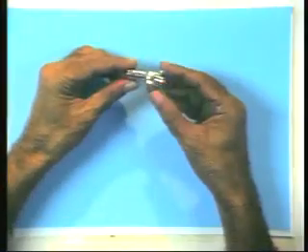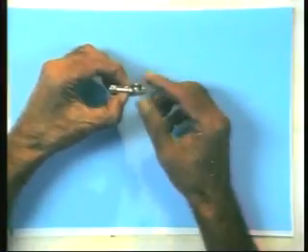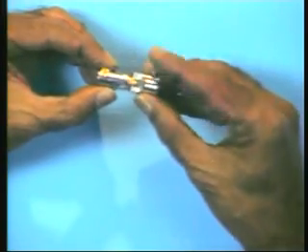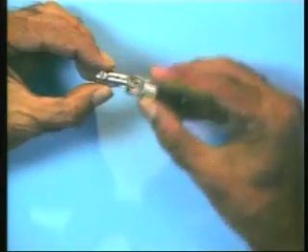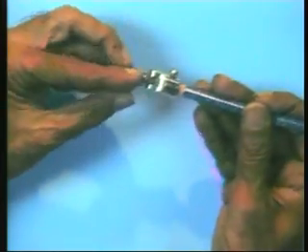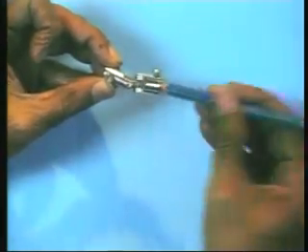See, here is a hook joint. Let me put that paper on top and show you the hook joint. It's a very tiny one. Now this rotation is possible. Also this is possible. That's all. This is not possible. There is play here. Otherwise this rotation is not possible. So how many degrees of freedom does it have? One rotation of this with respect to that. Okay, one rotation, and the second rotation. Only two are possible.